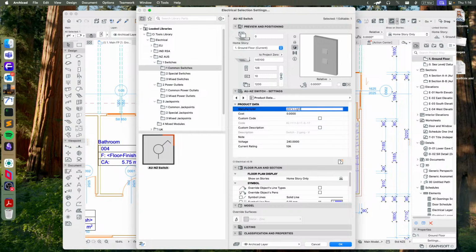But once I select it, you will see a fairly large amount of dynamic hotspots on it. And this is how you will edit the cable tray. I know that it looks like quite a lot, but once you see what they do, it will make sense. So essentially, we have 4 edges on this at the moment. So we've got one edge here, then we've got a junction and a second edge here and here, and then a third edge attached to the second edge up here.